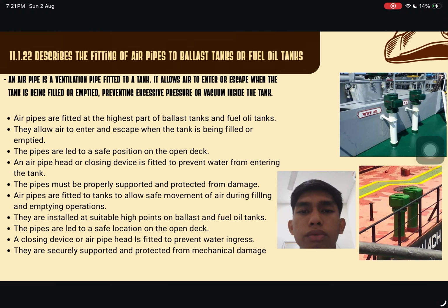Now I will talk about the fitting of air pipes to ballast tanks or fuel oil tanks. First, an air pipe is a ventilation pipe fitted to a tank. Its main function is to allow air to enter or escape when the tank is being filled or emptied. This prevents excessive pressure or vacuum from developing inside the tank, which could damage the tank structure.